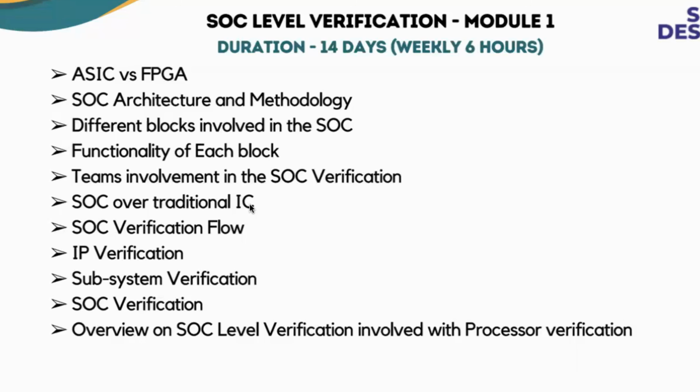And then IP verification: the difference between IP, subsystem, and SOC verification, we are going to discuss very briefly. And then the overview of SOC level verification involved in processor verification. What are the steps we need to follow? If you consider any block in the pre-silicon verification and in the post-silicon verification, what are the different things involved in processor verification? So overall, you will get the idea about verification in the first 14 days.